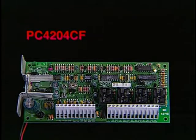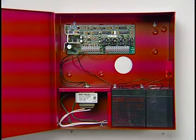The PC4204CF is identical to the PC4204 power supply module. It has 4 fully programmable Form C-type relays and is fully supervised for AC power failure, low battery, and aux output failure. The differences are that the module comes in a PC4052CR red cabinet with a hardwired transformer, and the aux output of the PC4204CF is limited to 550 milliamps.